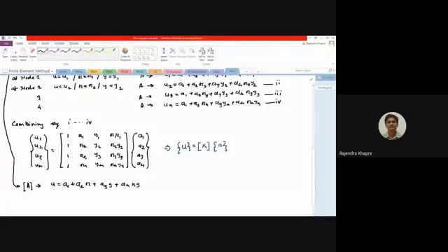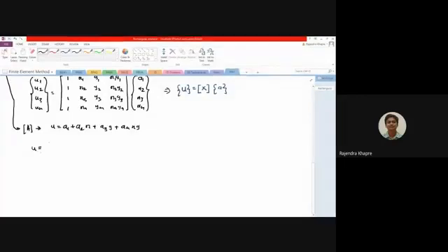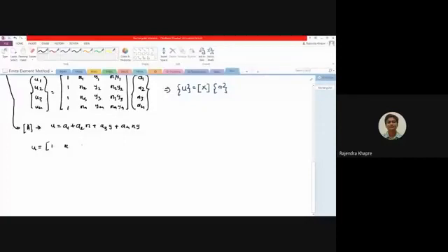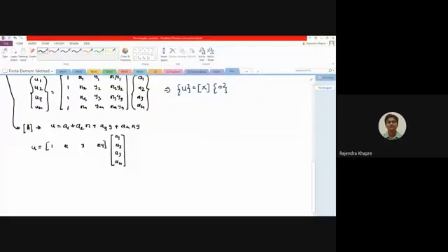What I am going to do over here is rewrite this expression a in a different form. This expression a can be written as something like this: 1, x, y, and x and y, multiplied by a1, a2, a3 and a4. I'm just rewriting expression a, the displacement polynomial, which is u. I don't know the values of a1, a2, a3 and a4.